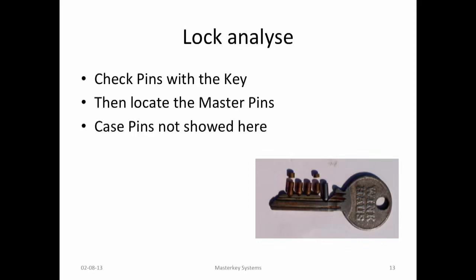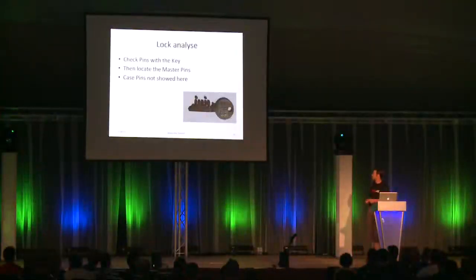Even if you have to do this, the cutting is always too low, so maybe a little bit of silver solder or hard solder will do, and just solder this position, and you can cut it at a higher position then.